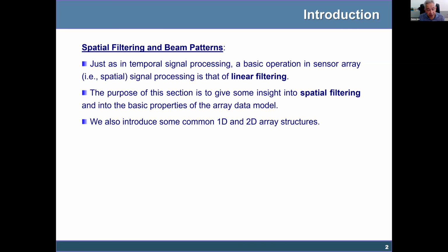You use a linear filter to enhance, to amplify the frequency components where the signal of interest dominates the noise, and you try to attenuate as much as possible the frequency components where the noise dominates the signal.